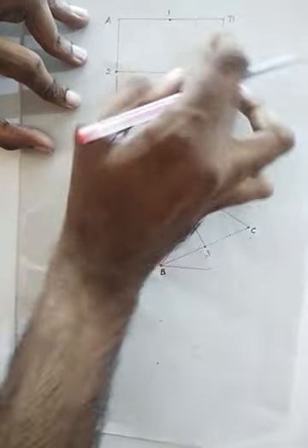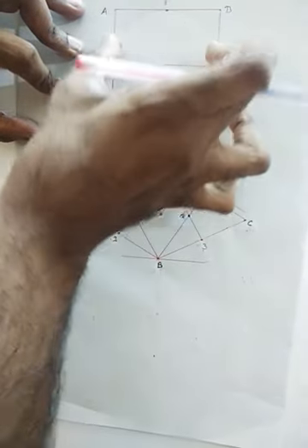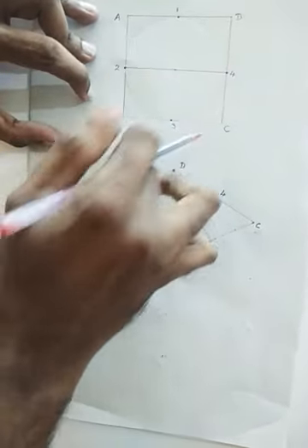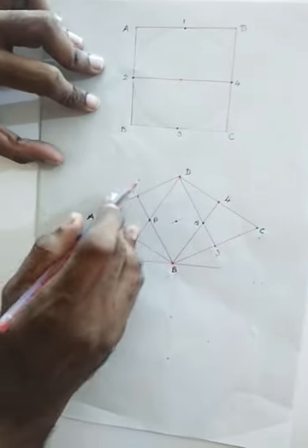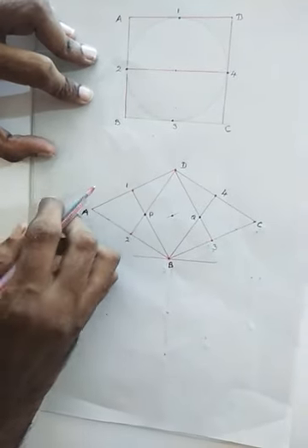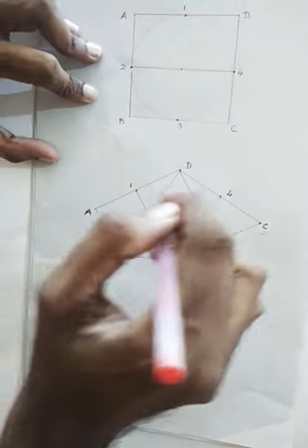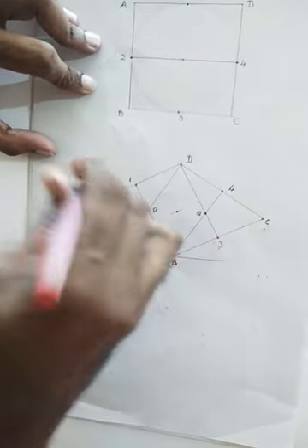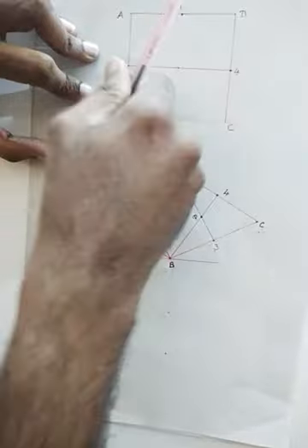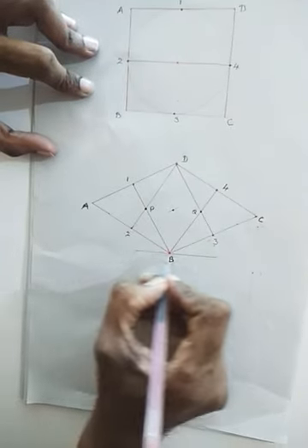Now we are going to tilt this square at an angle of 30 degrees. So automatically the circle also will get tilted at an angle of 30 degrees. When I am tilting a circle at an angle of 30 degrees, what we will be getting is an ellipse, and this ellipse we are going to draw by a method called the 4 center method. From the name itself we can understand we have to identify 4 different centers and we will be drawing the ellipse using compass itself.